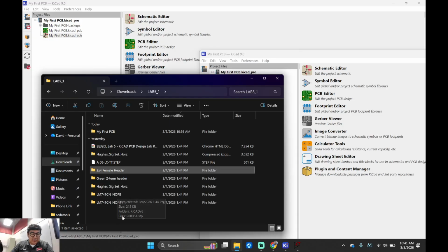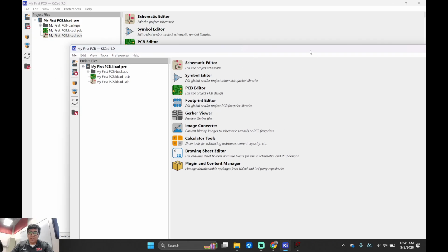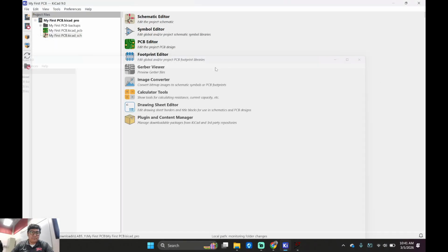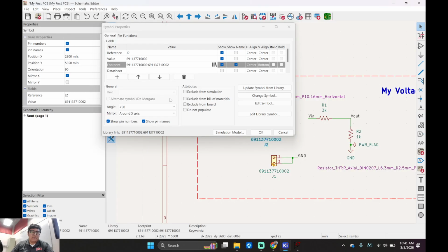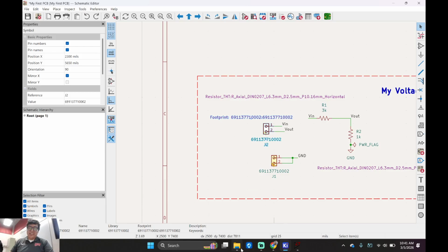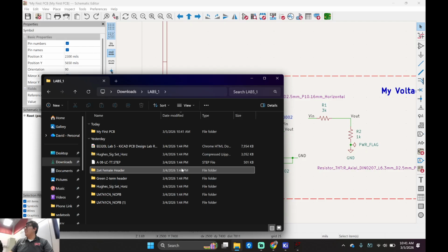And then I don't think the student downloaded the file I want, but we'll do it. We'll do it together, okay? So we're going through all the errors together. No. Let's go to your schematic. So let's go to, oh, this is very important. If you rename something in your folder, it won't change it in your path. Am I clear with that? If you change something right here, KiCAD doesn't know that you did that.